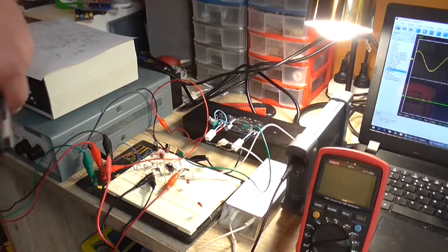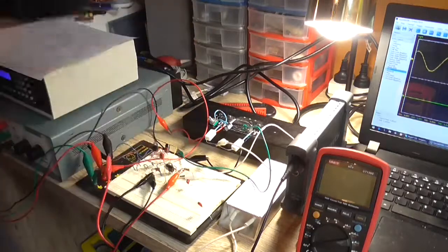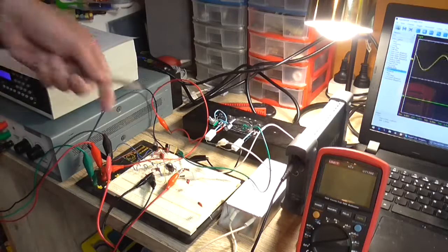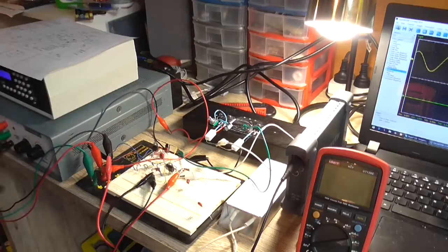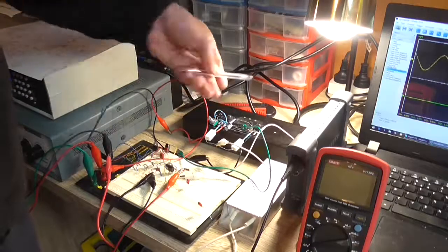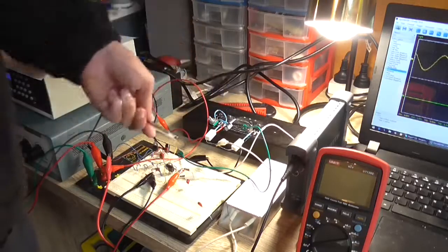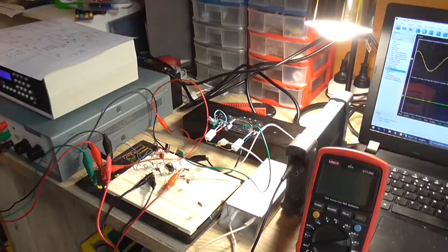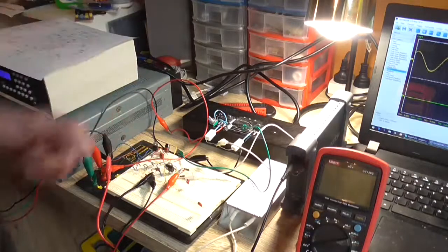So because you're driving a speaker, you need a lot more current to drive the speaker at the same voltage than you do off of the OpAmp, which is why there is an output stage here. Because connecting it directly to the IC itself will not make the IC very happy. It'll work probably for a few minutes, and then it'll just eventually blow the IC because it'll be getting red hot.